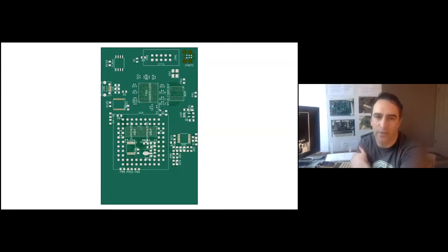So I started with the ULA footprint, added the FPGA, basically copied and pasted from my other project, the flash chip from ArcFlash. I spent ages trying to figure out how to fit a VGA output in there for video NULA support. Just couldn't figure it out. There was no way you'd be able to have a VGA cable coming out of the Electron's case. It would have to be some flat cable or something. I didn't want to drill holes in the case anyway, so I went back and forth on this for a while, and then eventually just punted on it and said, okay, let's just make it RGB only.